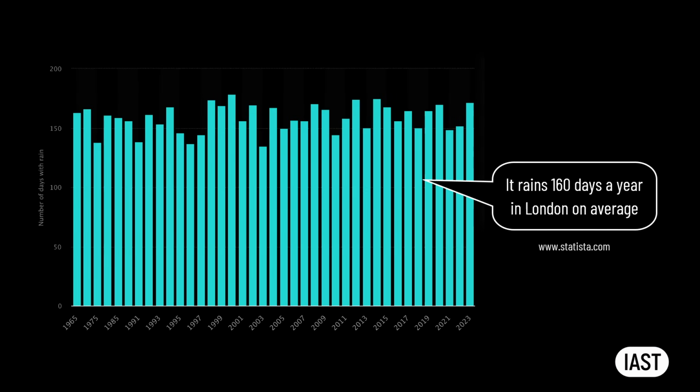All reasonable precautions should be taken to protect timber structures from elements during the transportation and assembly of the parts on site. However, given the significant amount of rainfall in London, it is virtually impossible to erect a 7-story timber structure without any of its parts getting wet. For this reason, provision should be made for compromised timber sections to dry before they are covered up with the facade and internal finishes. Timber is a combustible material.